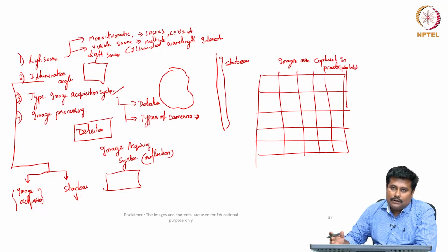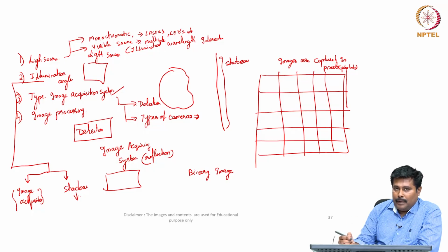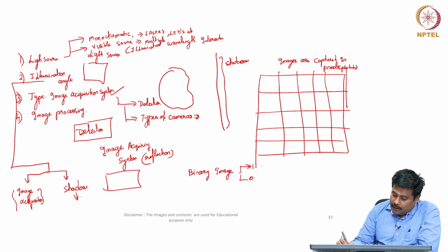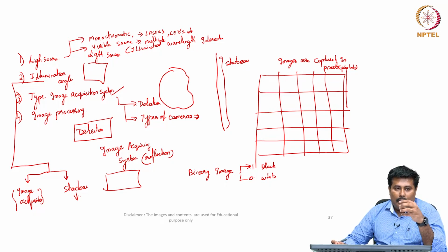There are different stages of image processing which are deployed, like we might have heard about the binary image. This binary image ideally comprises ones and zeros, which is nothing but either black or white. Wherever the light falls and the photodiode gets excited, it is considered white, or in certain cases wherever the photodiode doesn't get excited, it becomes black, or it can be vice versa based on our requirement or functionality.